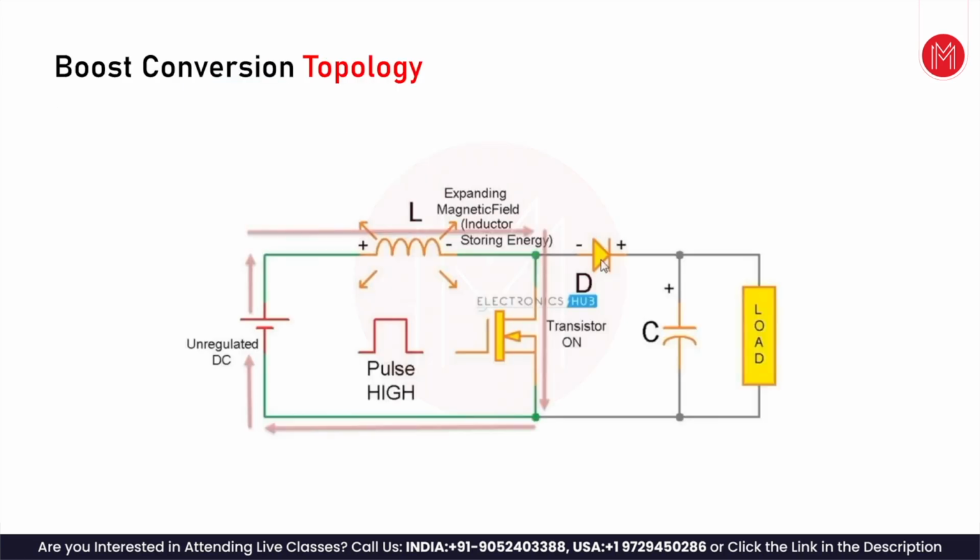In the boost topology, the inductor is on this side, and the capacitor is again on this side. During the on condition, the FET is turned on. So that means the voltage here is pretty much zero voltage, so it does not conduct here. And so the inductor charges here, and whatever charge is on the capacitor goes to the load. This is in the on condition.